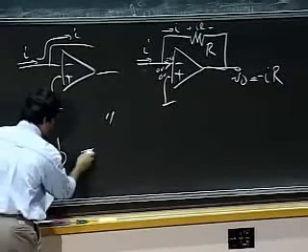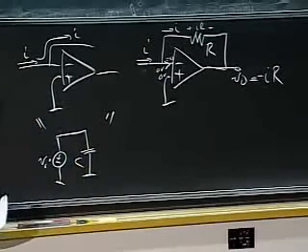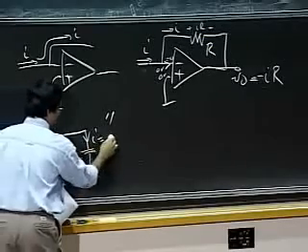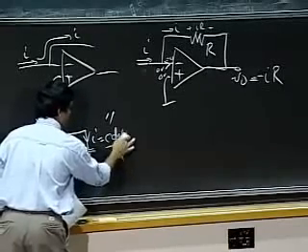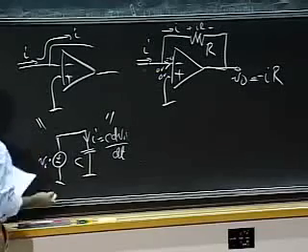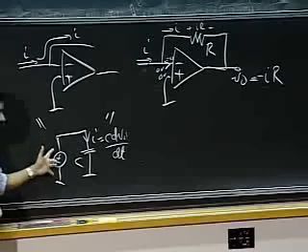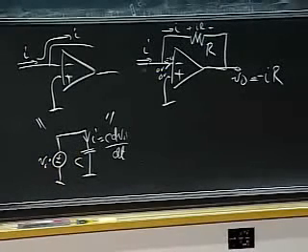And I know I can do that by simply doing this. By doing this, I know my I is C dVi/dt, correct? So I'm looking for a pattern where a voltage VI is directly applied across a capacitor, and when that happens, the current relates to C dV/dt.